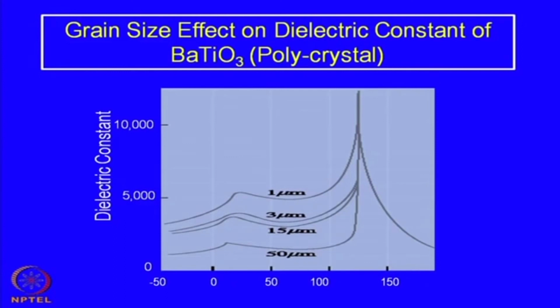So, many different compositions are available in the industry with different kinds of standards, and they are used for different purposes. Some capacitors require a very high dielectric constant so that miniaturization is possible, but whenever you have a high dielectric constant, the temperature dependence is also high, the temperature variation is also high, so they are not that stable.